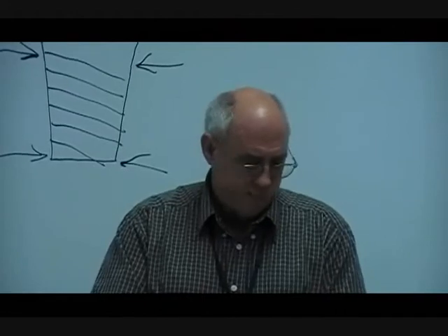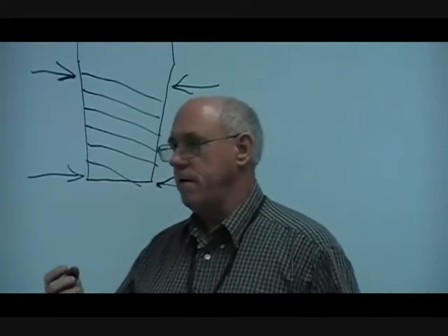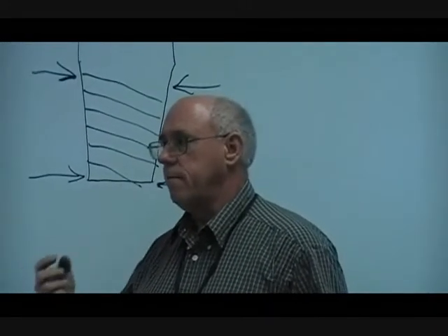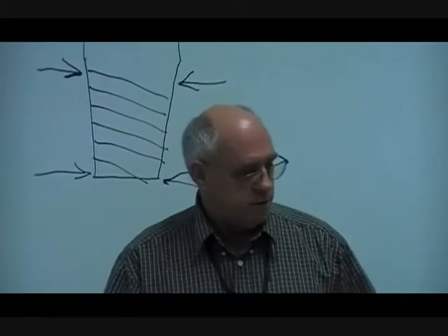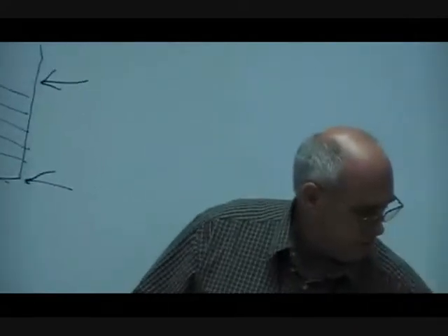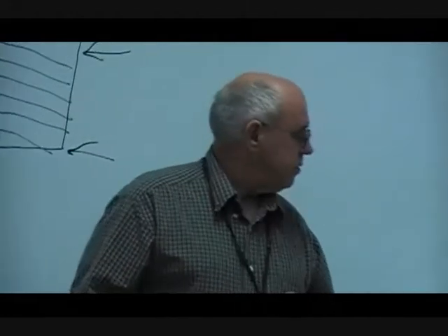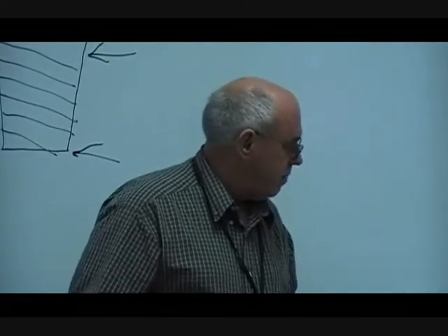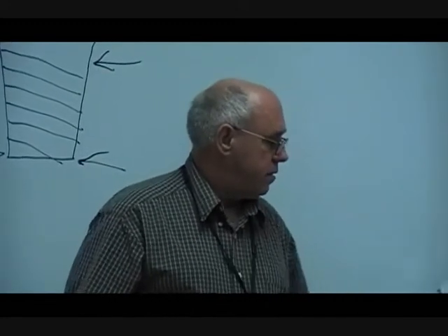One of the other things that I've run into, especially with some gas applications, is the restriction inside that valve may be large enough to cause a problem of pressure loss down the line. So just make sure that the fitting is rated for the material that's going to go through it and the pressure ratings. Okay, some of the other pipes that we see out there, I haven't gotten to the copper yet. We're going to do a little more extensive on the copper. But to cover the others,